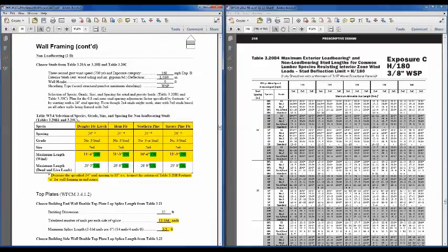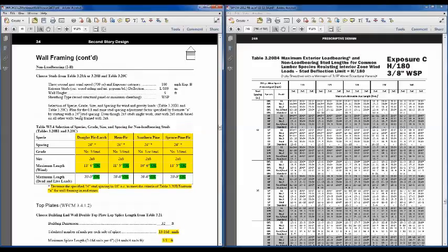So here in the workbook on page 34, I've actually solved the example using a 24-inch on-center spacing, knowing that that 0.8 factor is required. And so that backs it down to 16 inches on center.